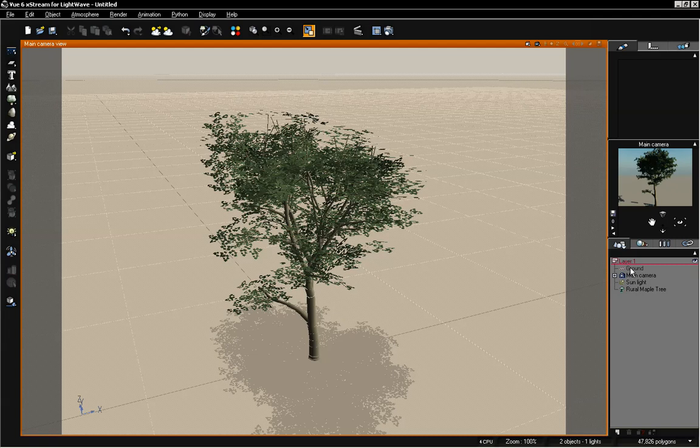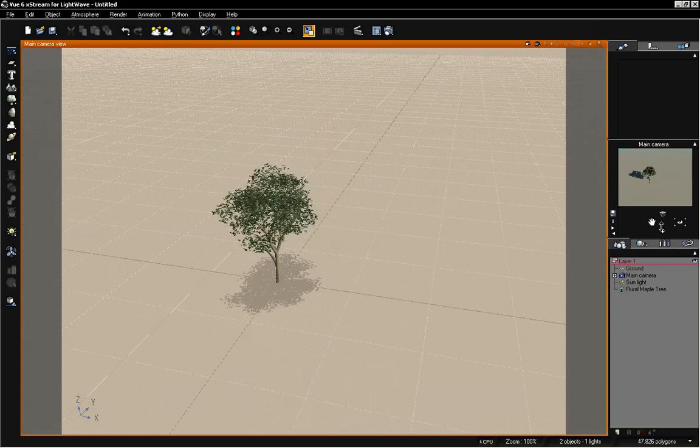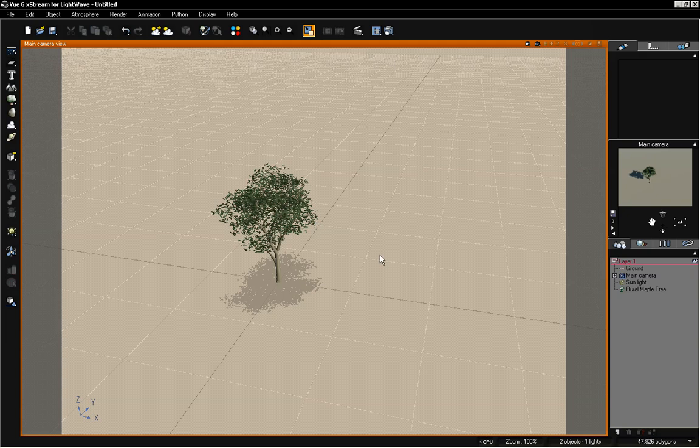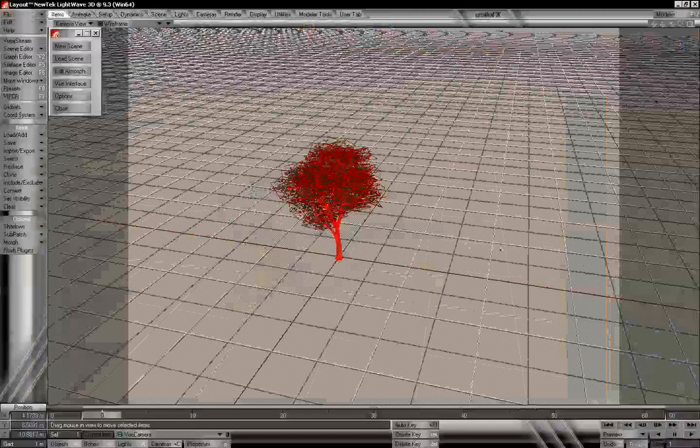hasn't updated. And one way we could easily fix this is just to click on the zoom, or actually the move function of the camera within our controls. And if you just do a quick click on that, it won't move the camera, but it will refresh the OpenGL. So sometimes you do have to sort of click on that. Another way is just to select an object usually.